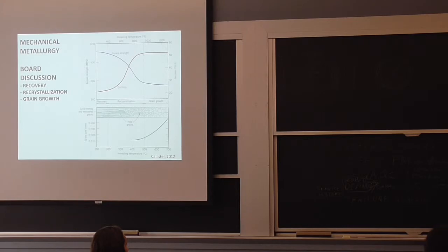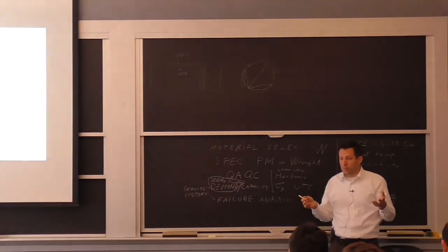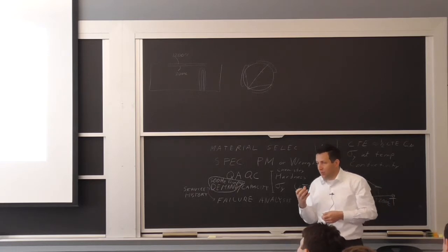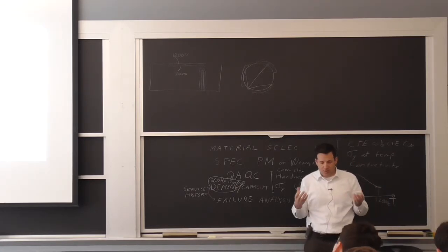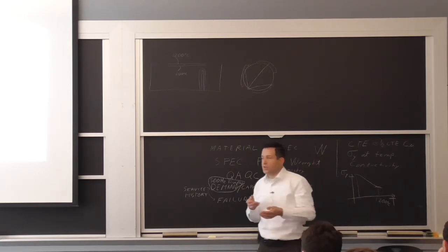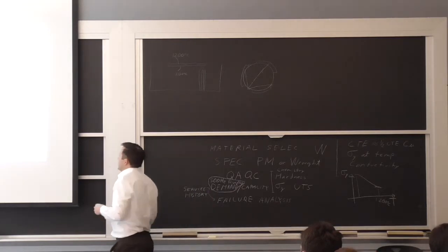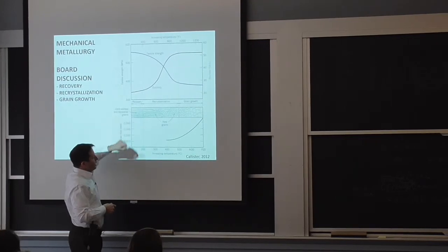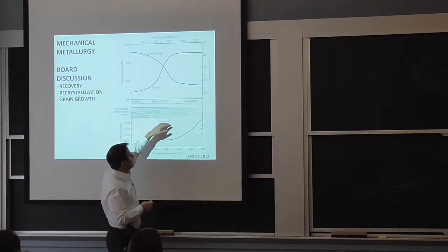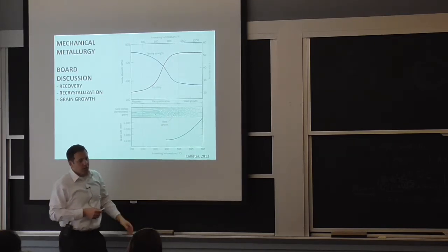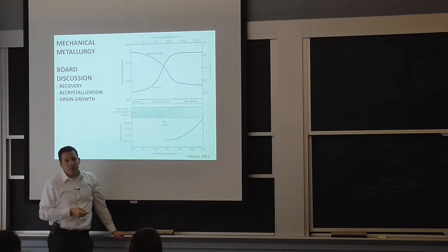What we generally do is we don't get the billets to just sit there in an oven, because we also want to tailor the microstructure, get very fine grains. And one way to get these fine grains into steel, for example, is to keep deforming. And you go through a certain cycle where, depending on the temperature you're at, if you're cold, you stretch the grains. If you continue at a higher temperature, you keep forming new grains, that recrystallization, and that happens in what we call hot forming, hot rolling.